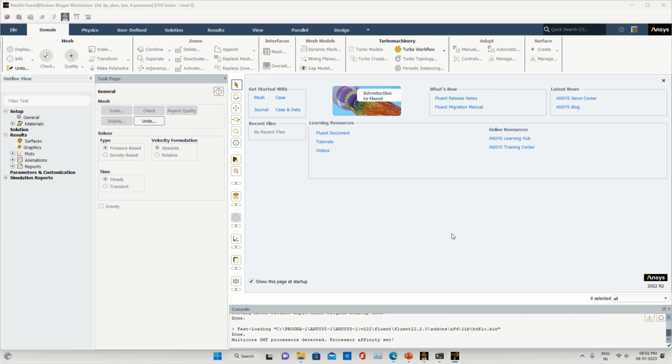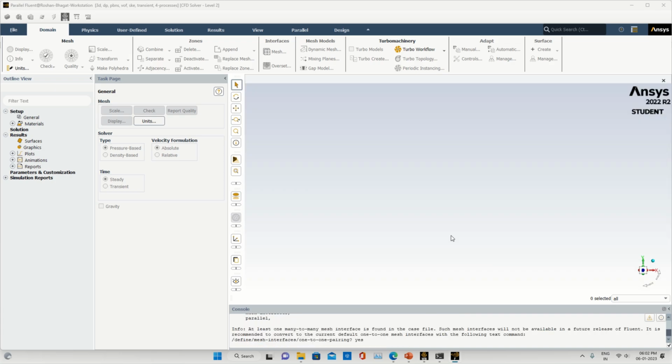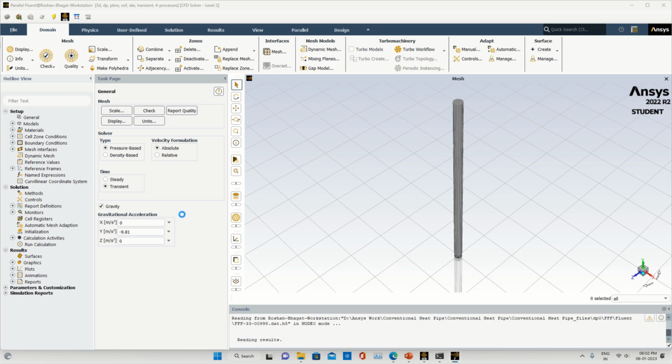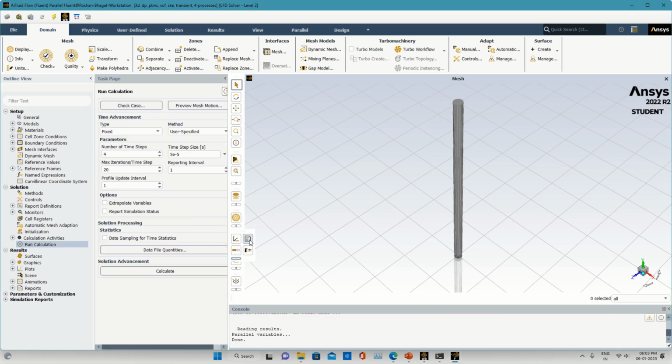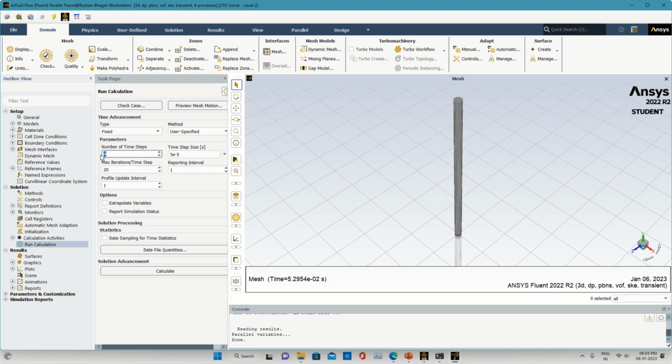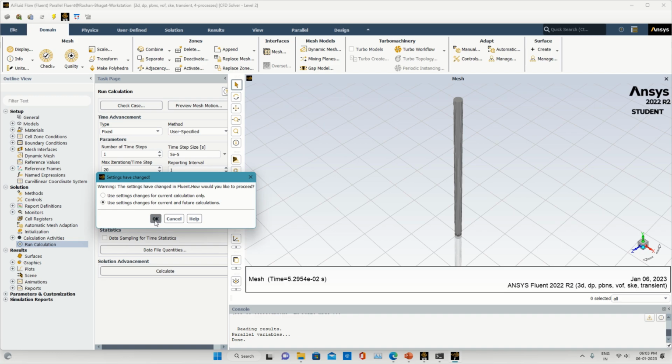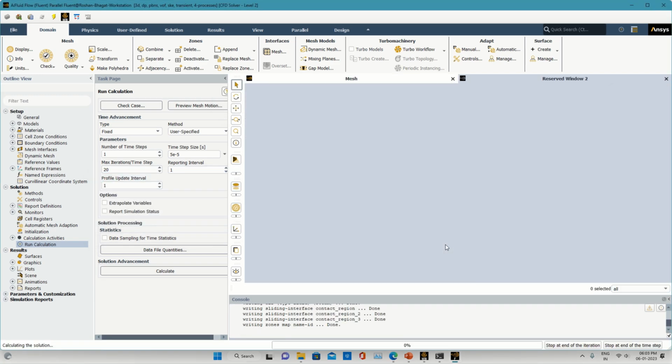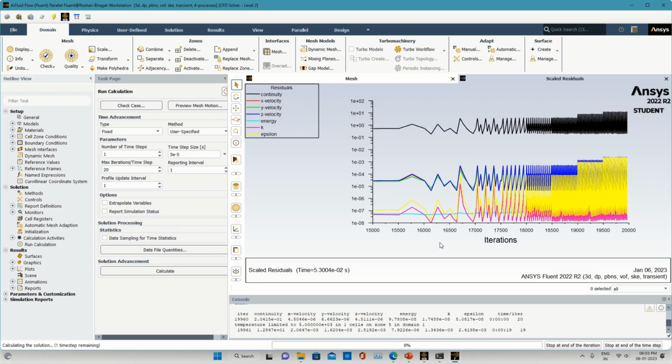So if such a problem occurs where we cannot reduce the time step and still we want to continue with the simulation, what process do we need to follow in order to proceed further? So let's make it okay. So instead of specifying 4 I will specify 1. Okay, now I specified 1. I will check whether it is able to solve it for us or not.